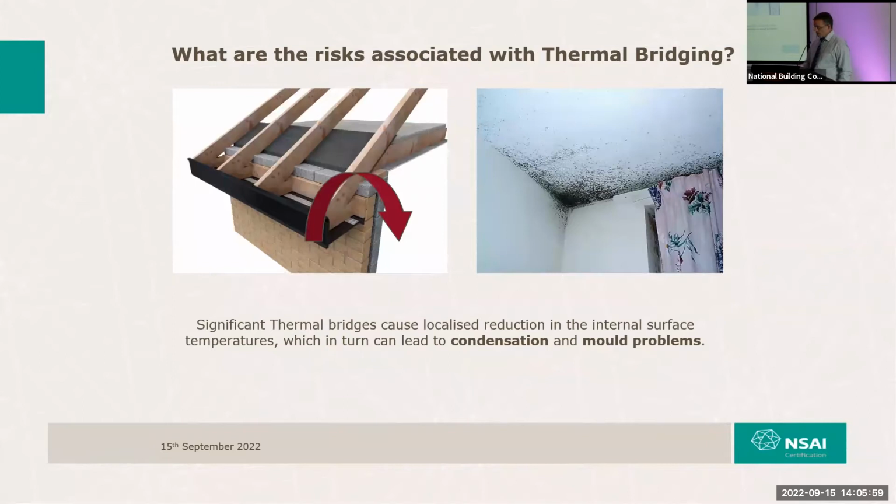Again, we've touched on the risks of getting these details wrong. It gives rise to large thermal bridges. This introduces internal cold spots on the internal envelope of the building, which give rise to condensation occurring, which in turn propagates mold growth, and gives rise to an unhealthy living environment, respiratory problems, asthma, COPD, and various other undesirable toxins in the air.